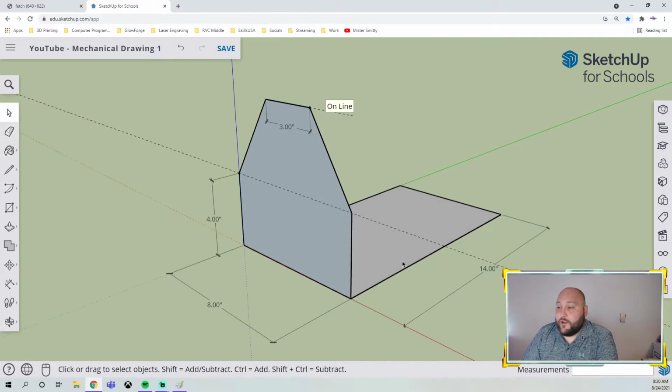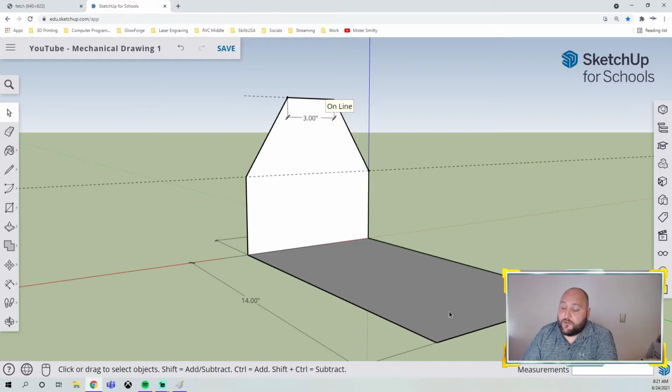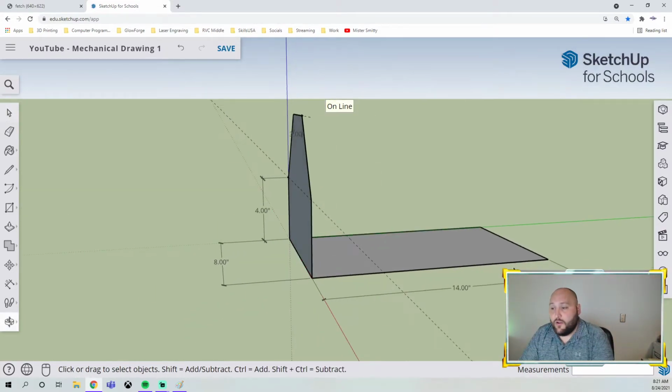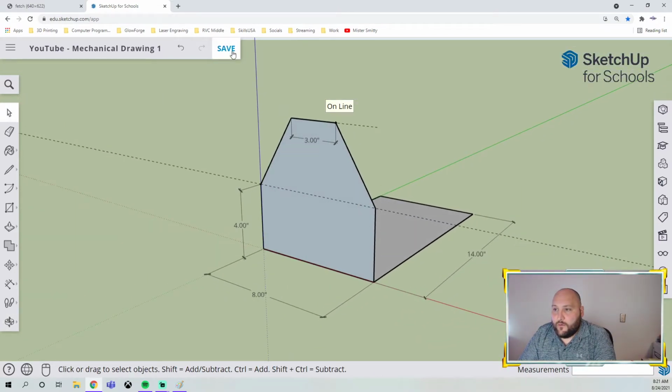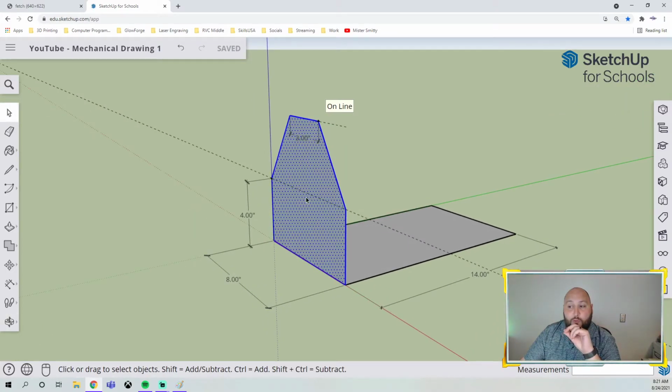At this point, we have half the box created. We could go to this side and redo all those steps to make the entire side piece again. Or, if we go up here, I'm doing a quick save, and double click this. Remember the types of clicks. The first click highlights the plane. Double click, you get the plane and the outline of the plane. And triple click is the whole object. So you want to double click because we just want that one side.